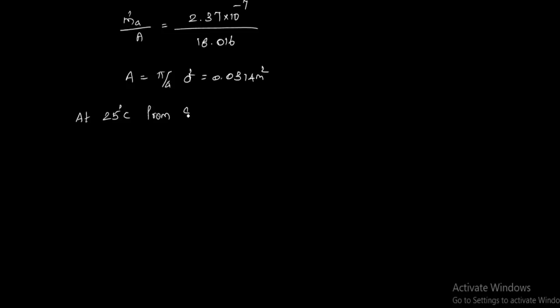From steam table you know that PW1 equal to 0.03166 into 10 to the power 5 Newton per meter squared. In the outside it is dry saturated air, so PW2 equal to 0. Okay, now substitute all the values in this formula.